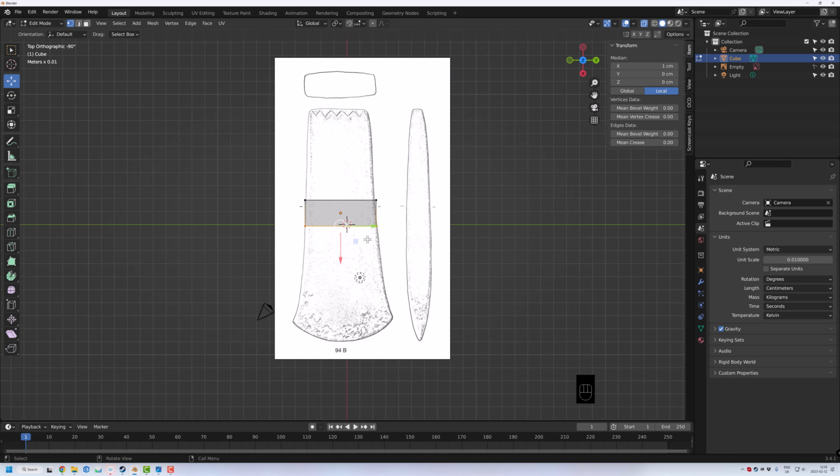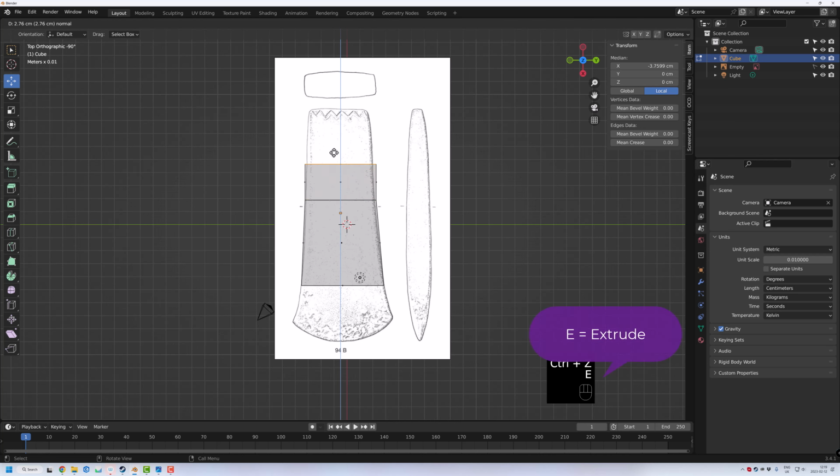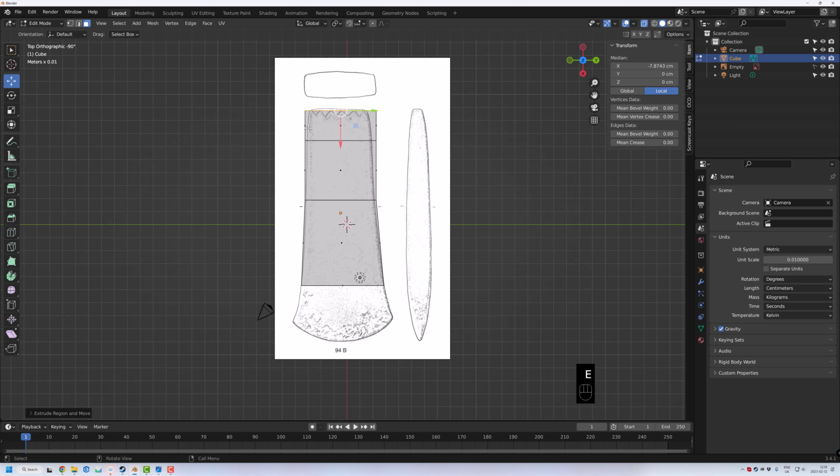Then I will select the vertices, move them down to somewhere around here, and take these two and move them out so they roughly match the edges of the shape. I don't want to be too perfect here, but it's good to get a rough general shape. Now I'll press 3 so I can select polygons, and I will drag out to select this one. Press E to extrude out, maybe to somewhere around here, and then do one more so I get the end as well. At the front I'll do the same and go to roughly here, I would say,